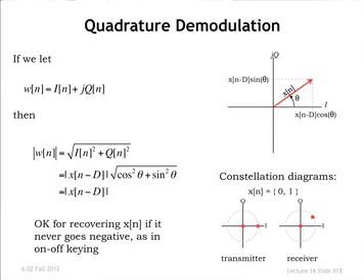So this is fine. So what you will discover is that you get some signal out there, and you're looking for its length. When the length is non-zero, you say you have a 1 sent. When the length is 0, you say that you have a 0 sent. And in the presence of noise, of course, it won't be exactly at the origin. There might be some cloud of points there, and similarly for the one level.